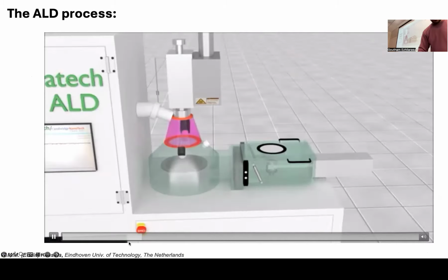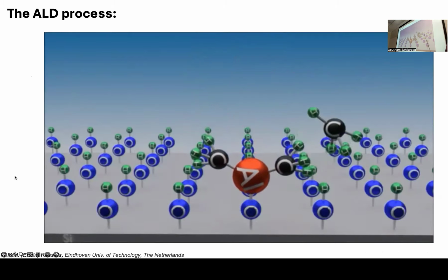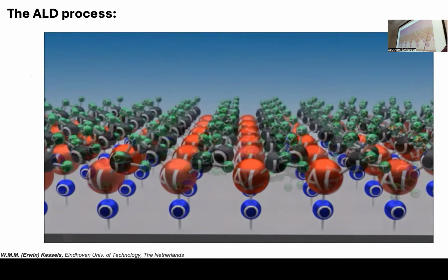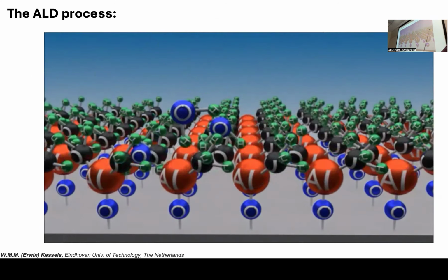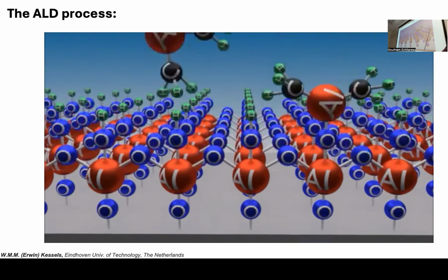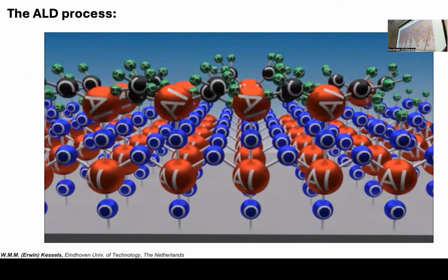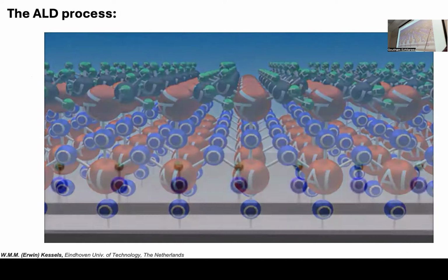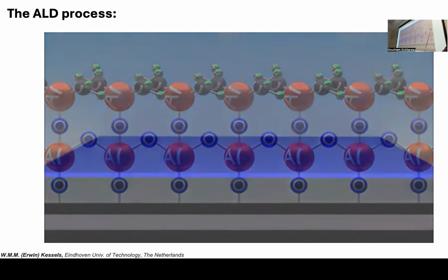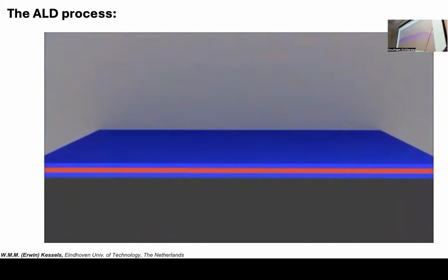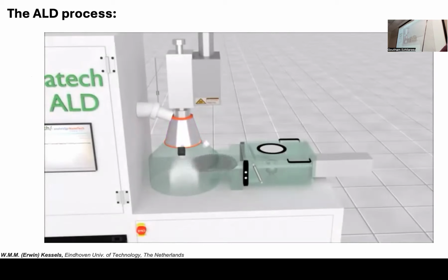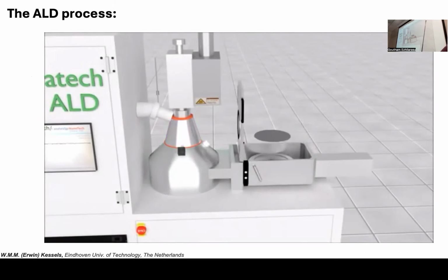Atomic layer deposition. ALD has the unique property of having self-limiting reactions, which allows for precise growth control over complex structures. Precursor molecules are delivered by an inert carrier gas and will react with all available surface sites, after which the reaction terminates and excess material is purged from the system. This occurs for each precursor type, resulting in the growth of a single atomic layer. This binary process repeats itself until the desired film thickness is achieved. The properties of the ALD film can be optimized based on the different deposition conditions, including the material source and deposition temperature, which can be as low as 50 degrees Celsius.